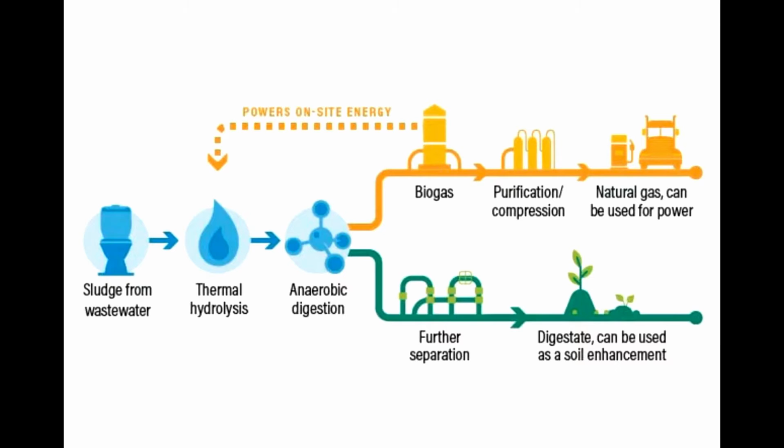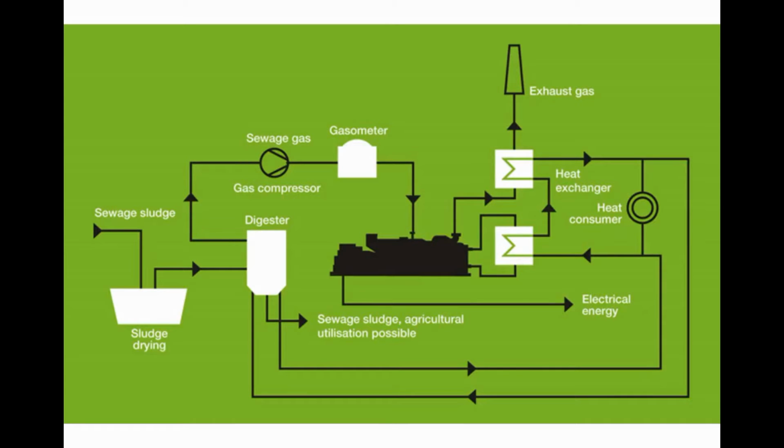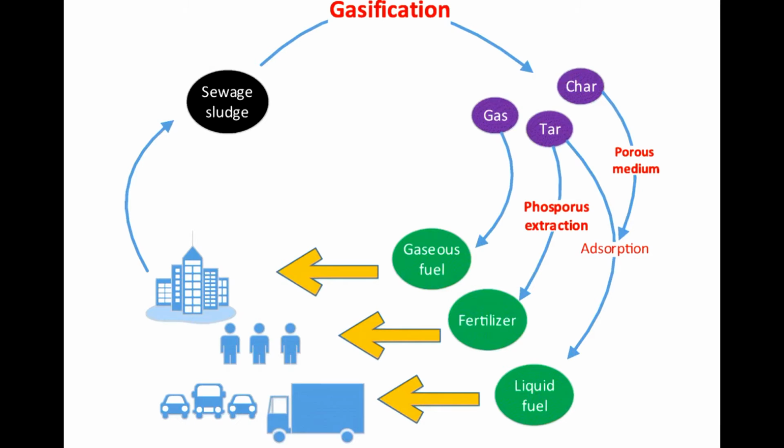It is treated with anaerobic bacteria in specially fully enclosed digesters heated to 35 degrees Celsius, an area where these anaerobic microorganisms thrive without any oxygen. The gas produced during this anaerobic process contains a large amount of methane, which is harvested and then burned to generate electricity. This energy can be used to power the wastewater treatment plants, making them self-sustainable, and if there happens to be an excess of energy produced, it could be transported into a country's national grid.